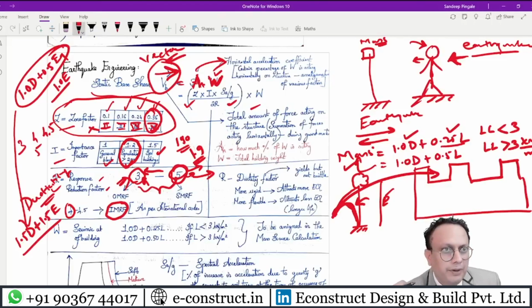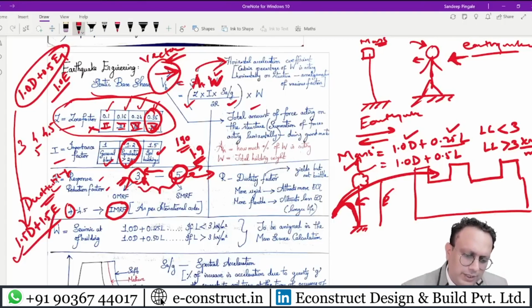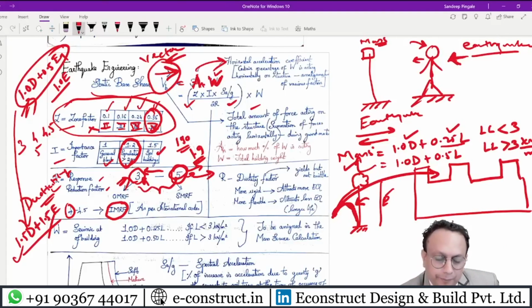Somebody will say that it is because of the seismicity in Dubai and many other places. But I think we should learn many things from the already developed cities and countries, and give a little bit of leverage in certain areas so that it will not be a loss to the economy. In general, the Indian code is very conservative. First of all, you can see 1.5 times dead load plus 1.5 times earthquake load, whereas as per the UBC code, this is the clause. And in many other cases, you will see this kind of injustice when it comes to codal compliances.